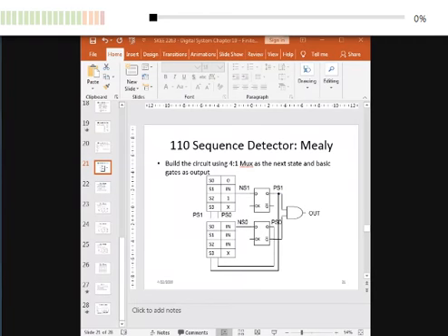What control unit do you need? If you look at the analysis in notes week 7 or 6, I don't remember. We must be able to control the data path in such a way that first we add, then we load, and then we shift. And you repeat this process 4 times. So your control unit should have the main control unit that produces the sequence, and then another control unit to count how many loops you have done.